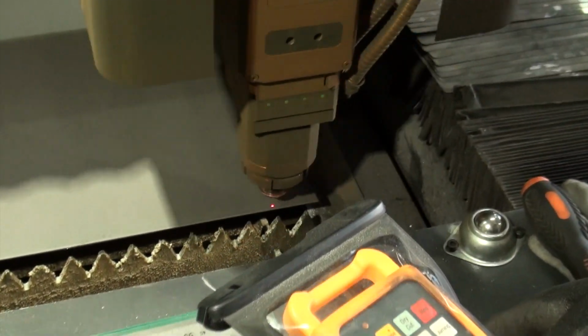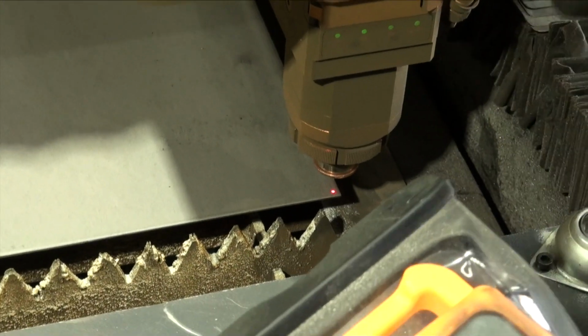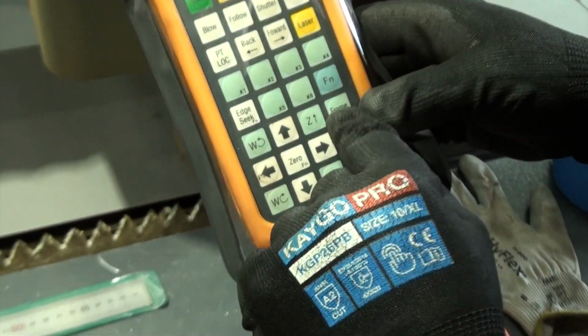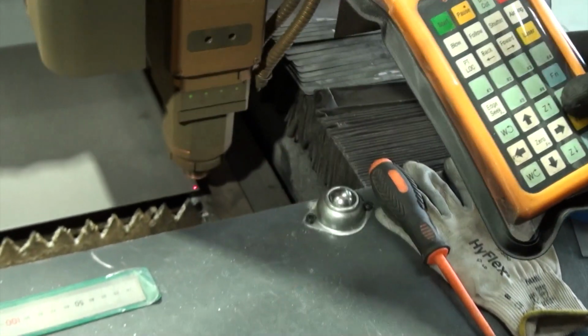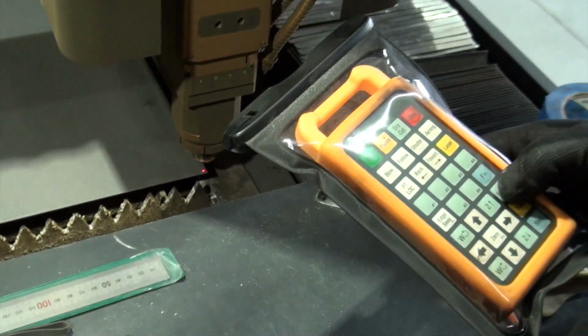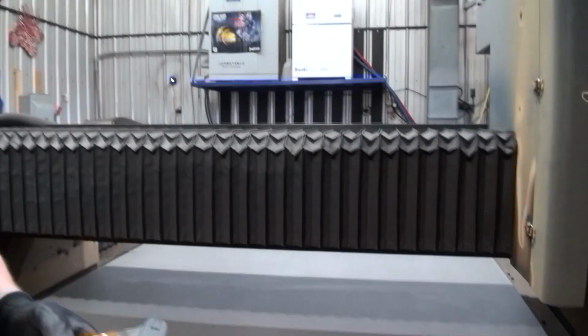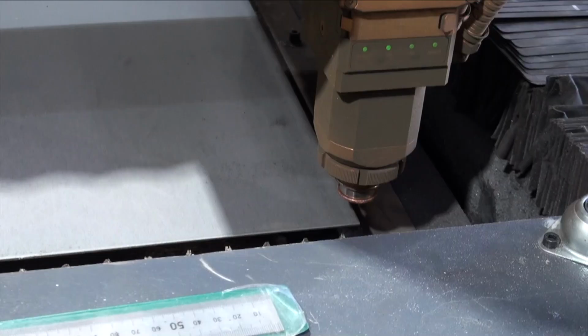We'll make sure that our outline is correct and we're not cutting off the plate by hitting the frame button on the controller. You hit the frame button and it gives you an outline of what you're about to cut out. Okay, now we're ready to cut our first coupon. We're going to go ahead and hit start, cut this thing out.